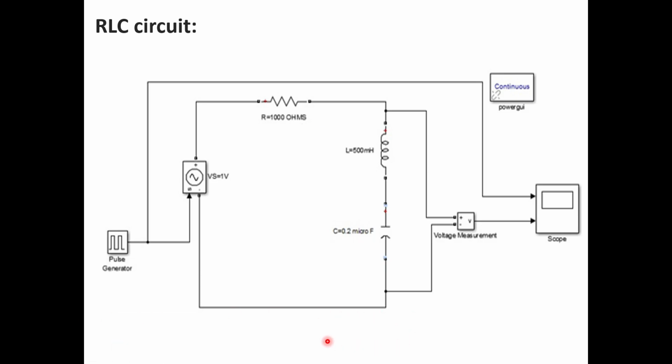So you can pause the video and copy down this circuit diagram in your notes. For each and every Simulink block diagram that you are going to design using MATLAB, you must also select this block from the Simulink library. This block is Power GUI.